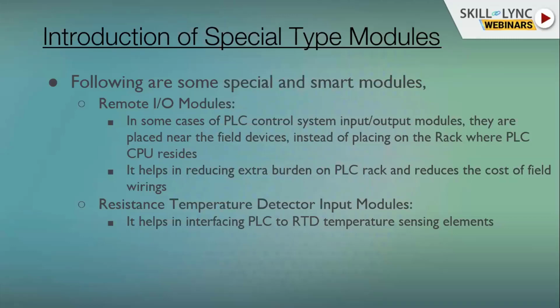If we want to wire their field devices to the PLC system, it will require a lot of wiring. So what we do is use remote I/O modules. As it says remote, it will not be closer to our PLC system. It will be nearer to field devices. From there, in a single wire, we get the status of the field IOs and send it to the PLC system.